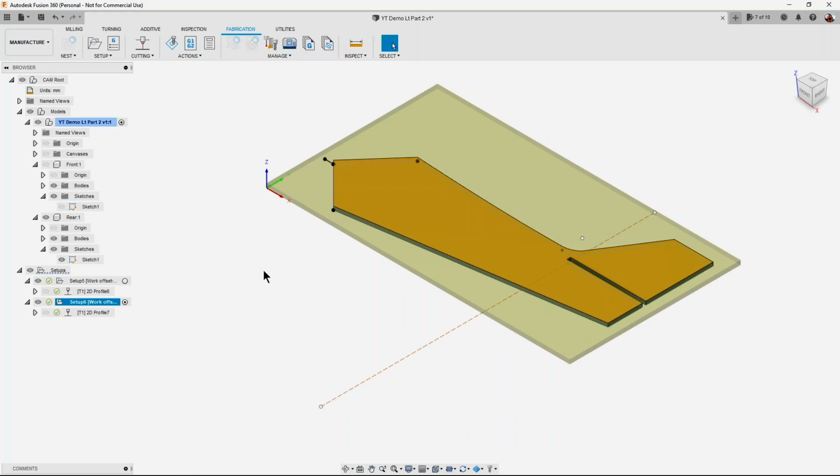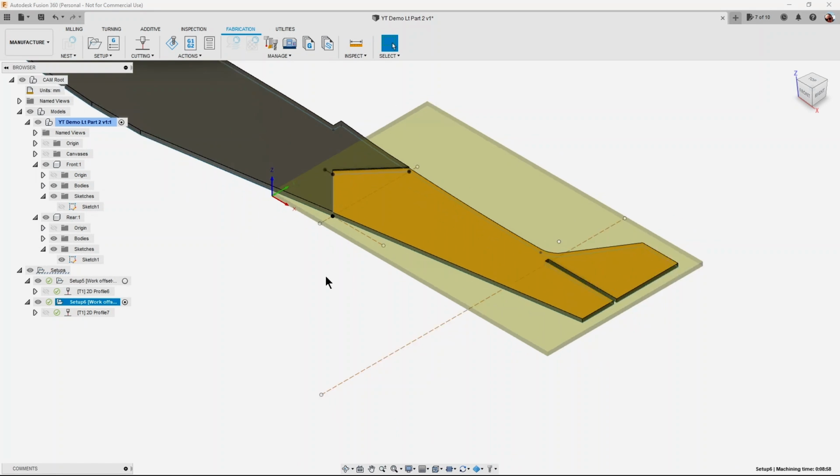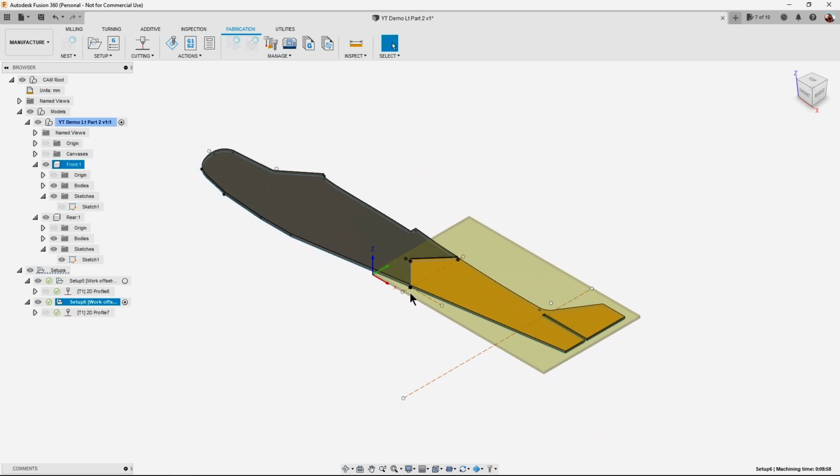And then what I'll do next is we'll jump onto the section where I show you how to get the rest of the dimensions out, to show you what size foam we need. So that's how we basically create two parts in Fusion 360. And the idea being is once we've got the parts out, we can then join them together there, and hopefully that should be a reasonably strong joint.